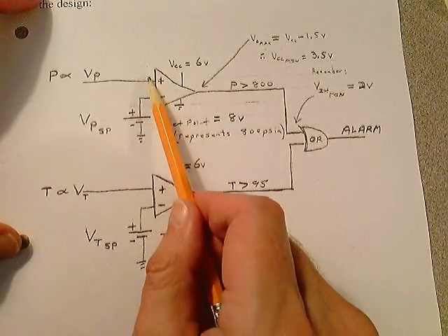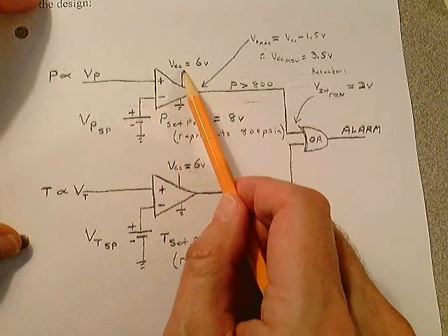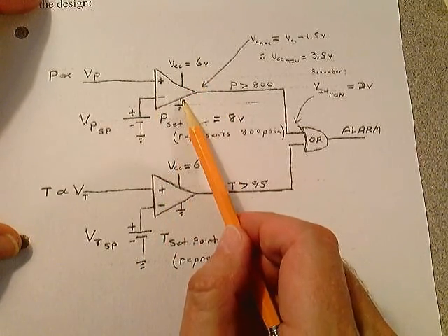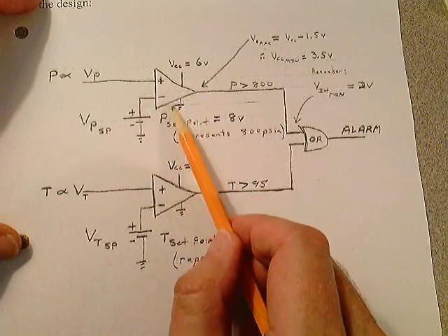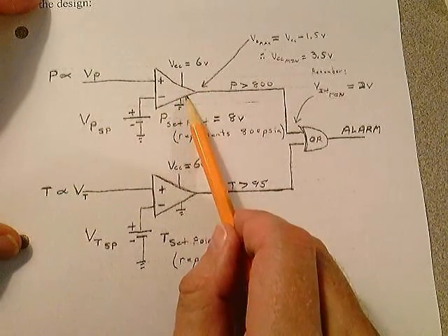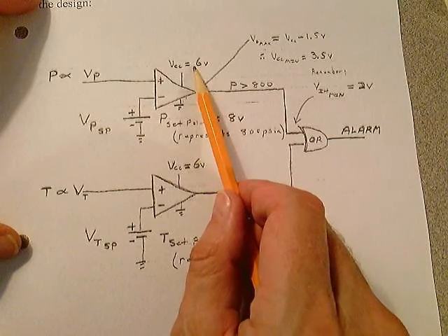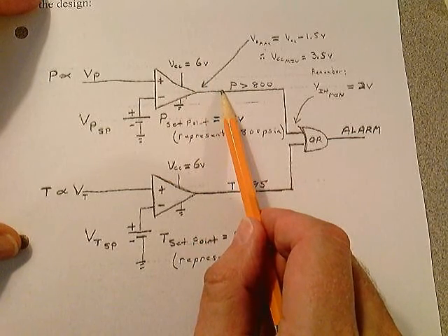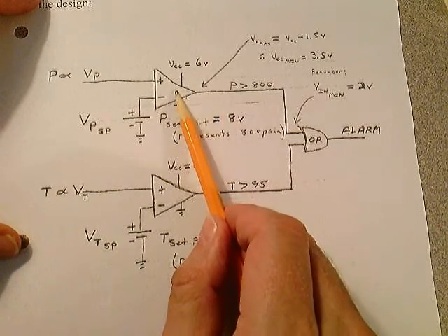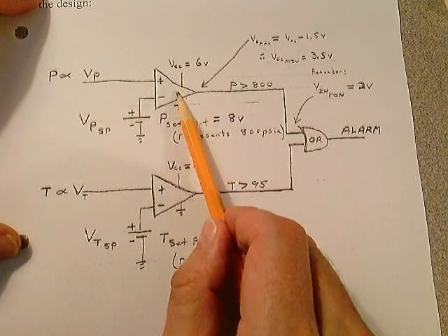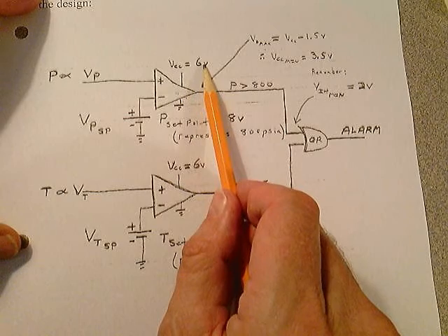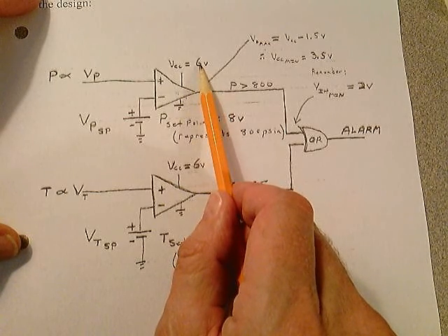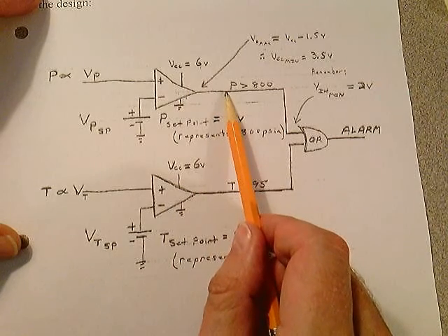What we want to do is run it into a comparator circuit. Now I want to set VCC up as plus 6 volts, and I'm going to set VEE up as ground. And you can buy op amps that'll do this. Notice that when you get within 1.5 volts of that rail, you're at 4.5 volts out here. But since we purchased these devices to get to the rail, you could bias this at 6 volts or bias this at 5 volts. And it'll work in a digital application.